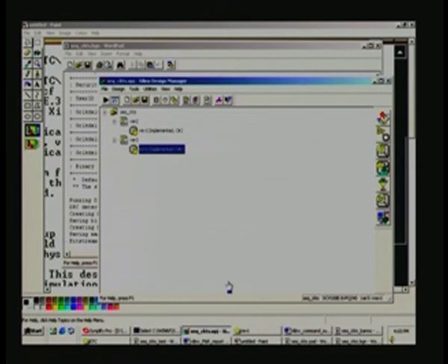So next what we will consider is the back annotation. We need to back annotate, because so far what we have done is only routed, placed, mapped onto a particular device, then placed and then routed it, and we need to get information for timing. For example, you want to get delays, so you need to have this what is called back annotated .v file created finally.